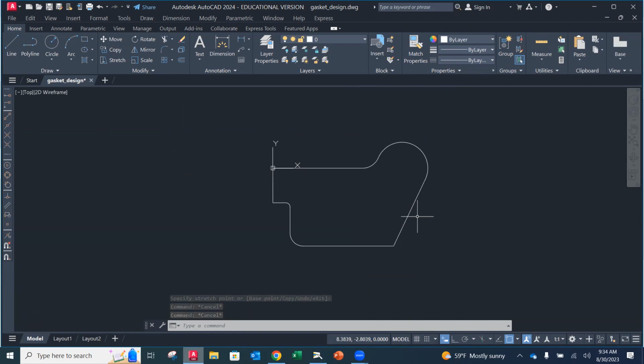It's a metal piece. When they do that, you need to export what they call a DXF file. The DXF file flattens this out and only gives the geometry. So if there are dimensions or anything like that, they're not going to be there. A DXF file is a profile that a machine tool can read, for instance a laser cutter.